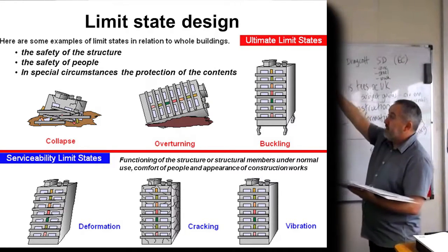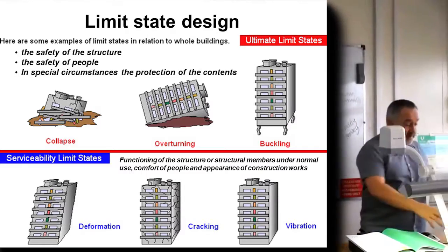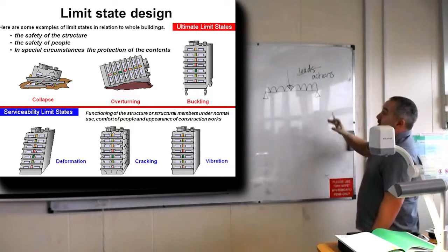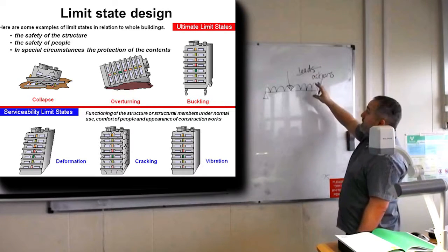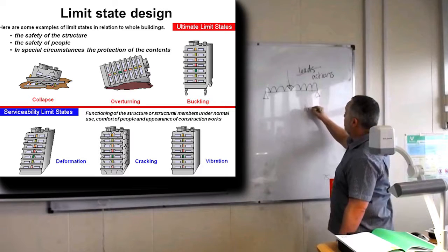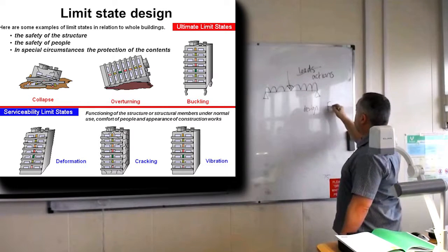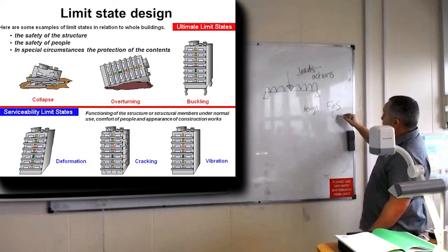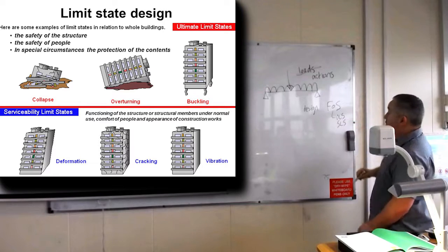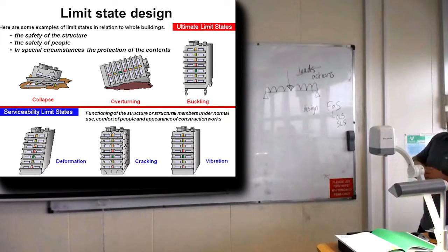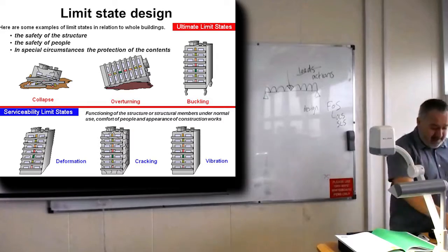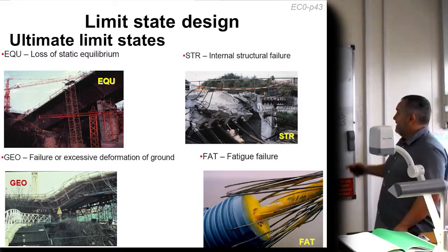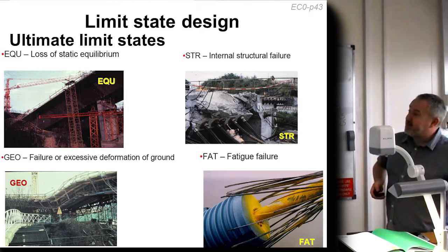But these things here give you different factors of safety to consider for your loads. That's what we do in terms of our structural mechanics. When we come to do the design, this is when you've got to start considering all the factors of safety. You realise that you've got your ultimate limit state and your serviceability limit state, and then it goes into even more categorisations to add more values for factors of safety.